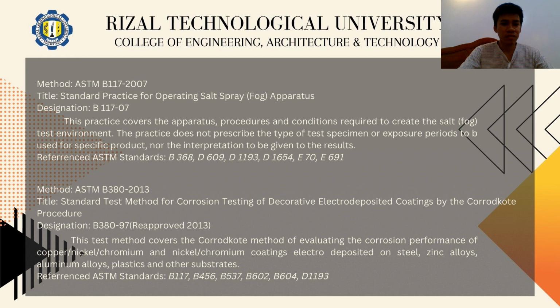B117-2007, Standard Practice for Operating Salt Spray Apparatus. This practice covers the apparatus, procedures, and conditions required to create the salt spray test environment. The practice does not prescribe the type of test specimen or exposure periods to be used for a specific product, nor the interpretation to be given to the results. This practice provides a controlled corrosive environment which has been utilized to produce relative corrosion resistance information for specimens of metal and coated metals exposed in a given test chamber.